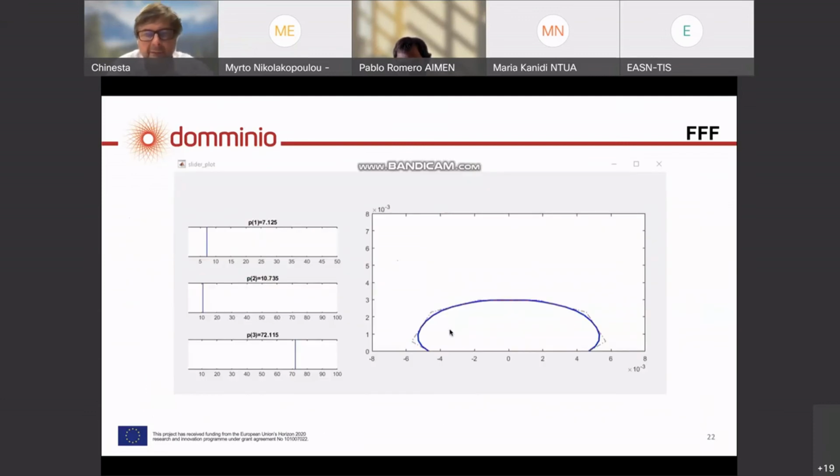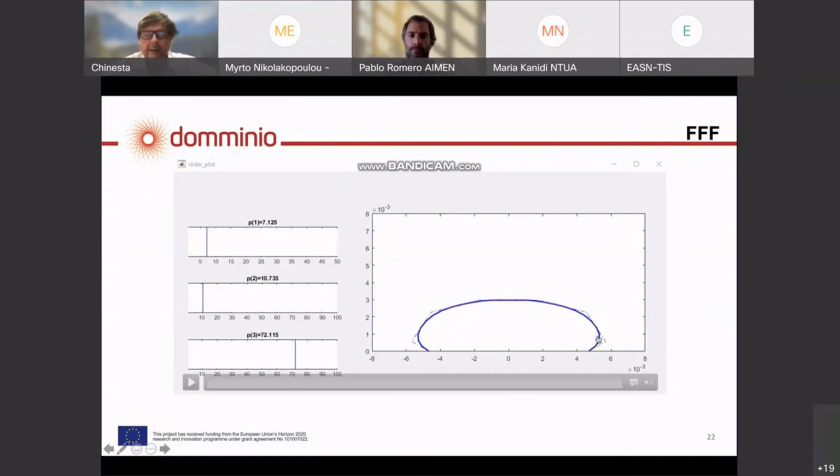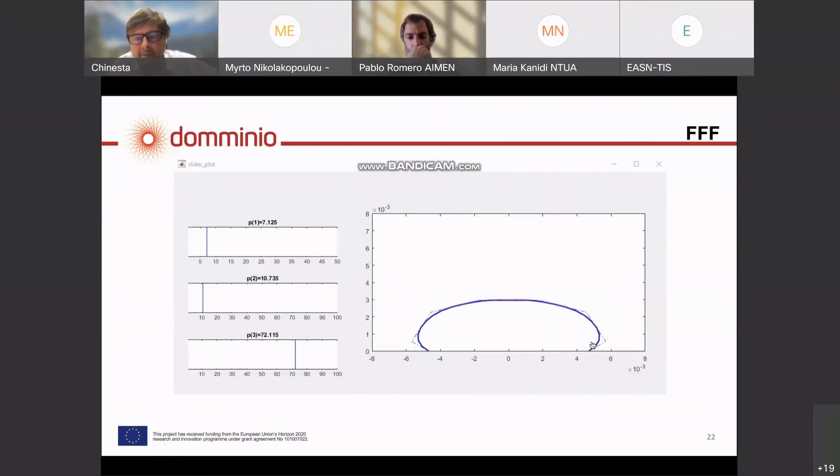And the idea at the end, and this is only a preliminary result, is to compute the final geometry of the filament, depending on many parameters, as just mentioned, the gap between the nozzle and the substrate, probably also the temperature at which the deposition is made, the temperature of the substrate, many parameters that we need to determine.